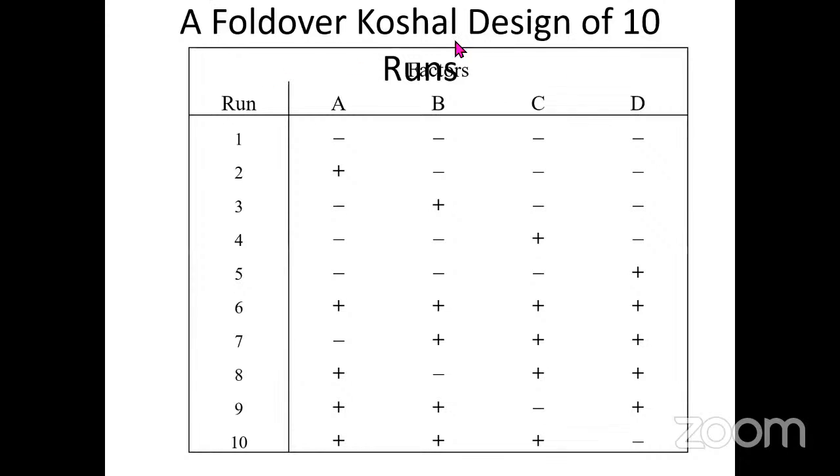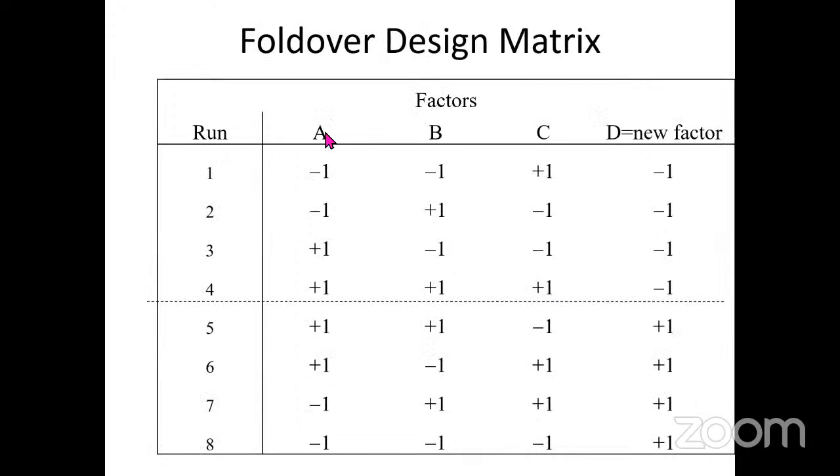And then this is called a fold-over design, and they give you how to run these experiments. So 10 experiments for 4 variables, then it's called a fold-over design. Again, this is say 4 variables, 8 experiments. But all the designs will always consider balance and orthogonality. Even in the fold-over design, you see the 4 pluses will be equal to 4 minuses. Check everywhere. Balancing and orthogonality are very, very important in the design of experiment study.